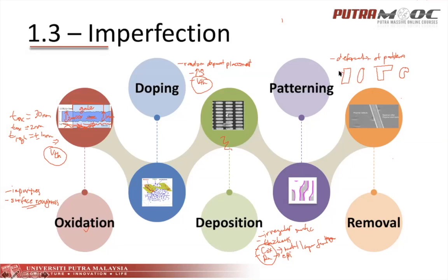It could affect, for example, if you have a diffusion area here and a diffusion area here. This one should be okay, because the active channel, which is here, and the one that is fabricated here, is within the spec limit. But if you have a diffusion area which is larger, and when you fabricate you have something like this, this kind of defect will greatly affect your transistor parameters.